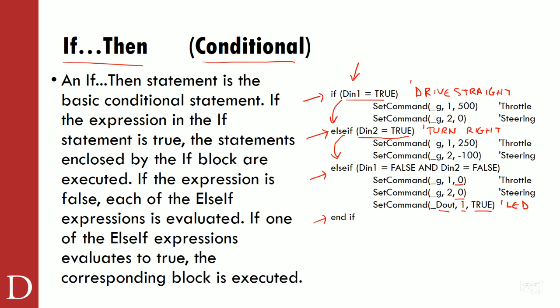I'm going to stay in this state up here. Else I'm going to this state, and if neither one of these two are true, then the condition is going to fall down here. So I've either got DN1 on and hopefully DN2 off, or maybe I have DN1 off and DN2 on, or maybe I have both of them off. I have not taken a true standpoint to what happens if both of them are on, but in this particular case, the if-then does do that by saying, well, if both of them are on, I'm prioritized on this one because it's the first one I'm going to execute.